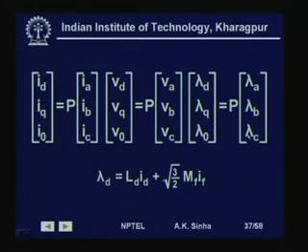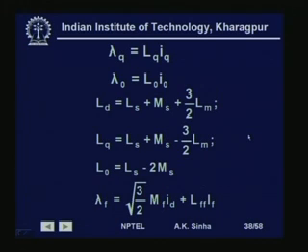If we use this transformation, then we can write all these equations for inductances and the flux linkages, and we find that in this case most of the inductances have become constant, because now the dq0 frame is also rotating along with the rotor. So, these time varying inductances are no longer there.